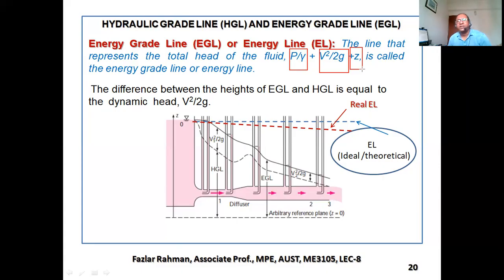But you cannot say like that. You have to say this is pressure head. And you say this is velocity head, this is potential head. And sometimes they ask, could you tell me the Bernoulli's equation in one sentence? So you need to say the summation of pressure head, velocity head, and potential head is always constant. That you have to say.